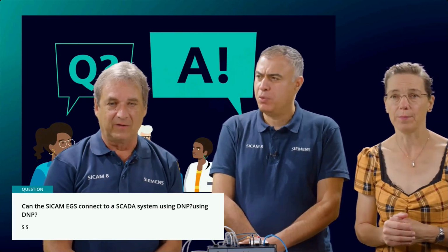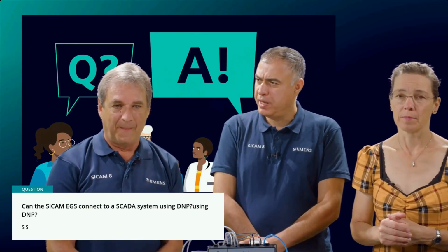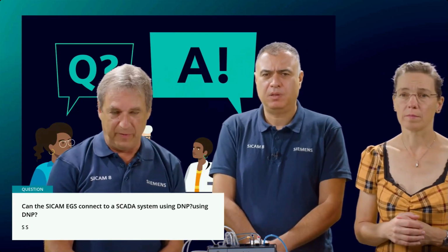And then the question from SS. I think it was also mentioned in the presentation, but we'll nevertheless focus on that. Can the SICAM EGS connect to a SCADA system using DNP? And I think I've seen it on the list, yes, right? Yes, they support DNP3 IP. It can be connected via the LAN interface here or via the LTE modem.